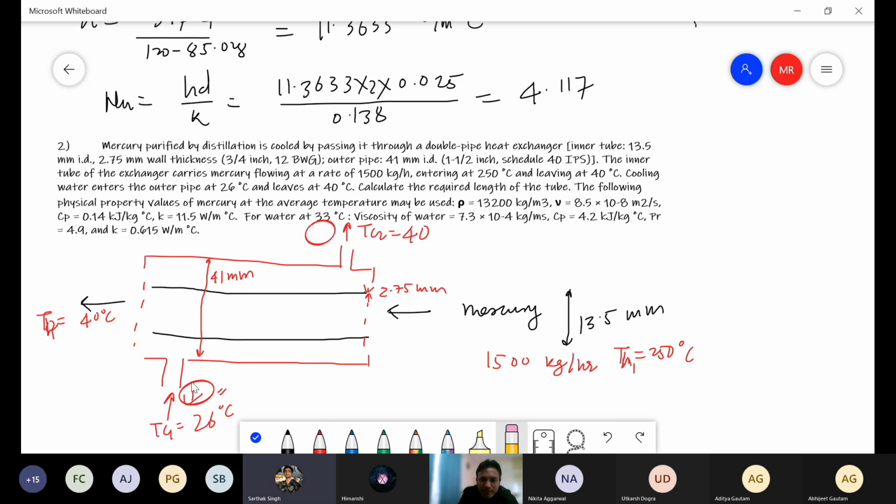Okay. So the outlet temperature of water is not in our hand, right? It depends on how much heat is transferred. But if I take the reverse way here, 40 degrees Celsius, remember from 26 to 40 it has increased, isn't it? Is it possible physically to have a temperature same as the hot fluid? There will be some resistance offered by the tube here. It cannot be, isn't it? So that's why that contacting is not possible. Only possible contacting is this.